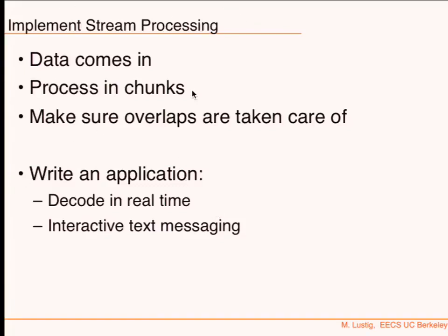The other thing that can happen is that you take a 1 second worth of buffer, you send it to the decoder. The decoder detects a packet just at the end of the buffer. Right? What's it going to do? So what we chose actually is, if that happens, it sends you a message: where did the packet start in the previous buffer? Then you can take those samples and concatenate them to the next buffer. Okay, but you have to think about that a little bit.